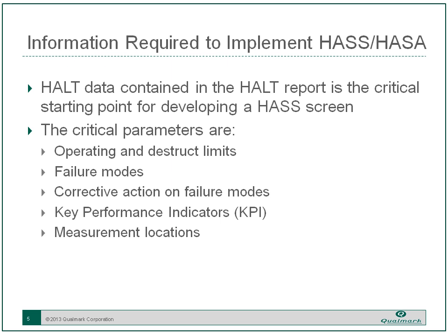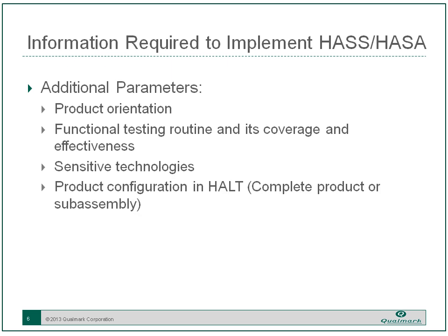On top of all the actual data recorded, the setup of the test in HALT is also very important. Locations of measurement sensors like thermocouples and accelerometers, product orientation and configuration, and functional test routines are all vital in recreating a test, as well as ensuring similar response when moving into HASS. And I probably should have moved over to this slide to say that.